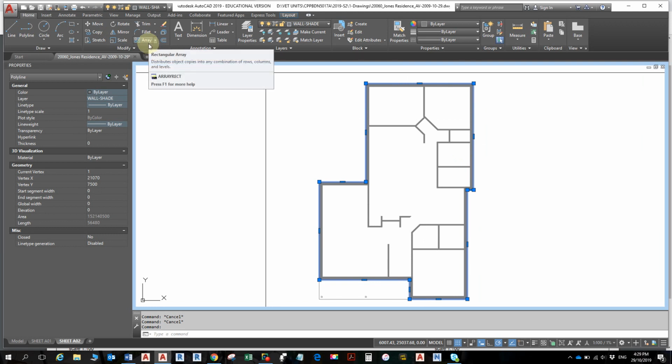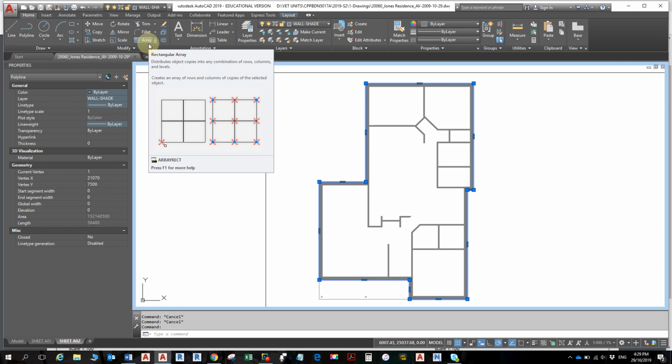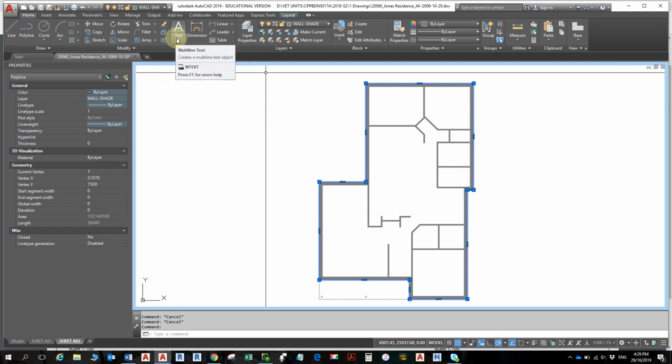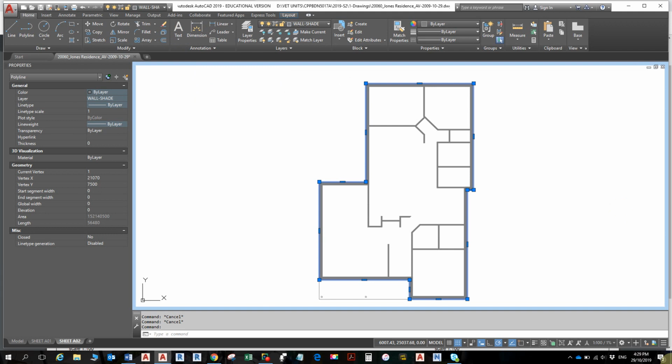Copy the what? Copy the layer, change the layer base. Well, the first bit I've got is copy and then change to layer, yes. And then paste, you said. No, copy, change the layer, and that's it. We stop there. Yeah, copy means change it to the right layer, basically. So that's correct. There's no such thing as copy it into a layer. It's not like offset, where you can offset it into a current layer. There's no command like that.